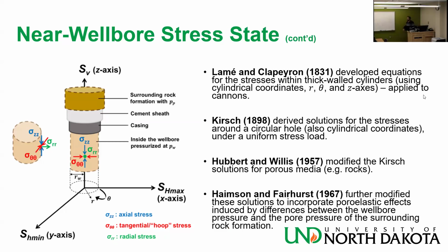Anyway, now a few years after Hubbert and Willis, we had two other scientists at the University of Minnesota, not far away from here, Bezalel Haimson and Charles Fairhurst. And they further modified Hubbert and Willis equations for poroelasticity. And that means fluid motion in and out of the pores, and the pores increasing and decreasing in size accordingly.